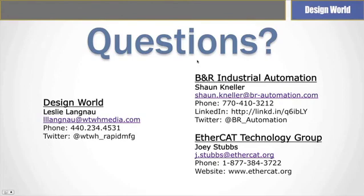Okay. This one is for Ethercat. Does the Ethercat process time increase with every added slave? By how much, since it's deterministic? And what is the maximum number of slaves on that network? Yeah, the maximum number of slaves on the Ethercat network is 65,535. That can be any device, so it could be drives, it could be I/O, it could be whatever.